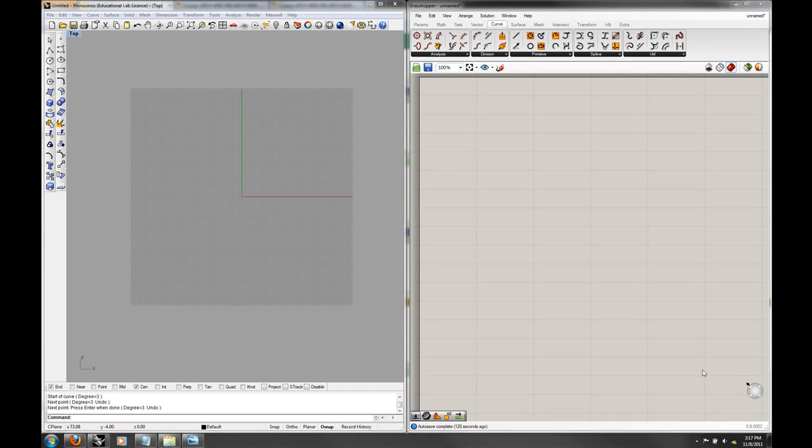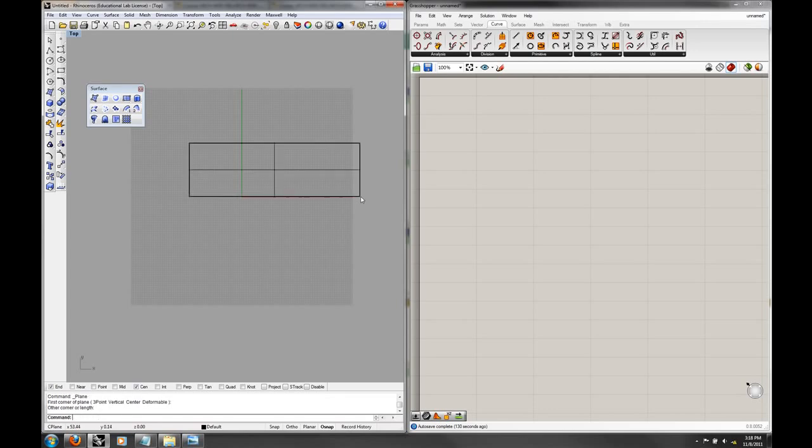So there are lots of different ways to start with a surface or to obtain a surface. If you look at the surface tools in Rhino, you can draw a surface as a rectangular plane. You can do a rail surface if you have cross sections in a rail. You could do a surface if you have the edges of things. You could loft something. You could extrude something. Surface from points. There are lots of different ways to look at surfaces.